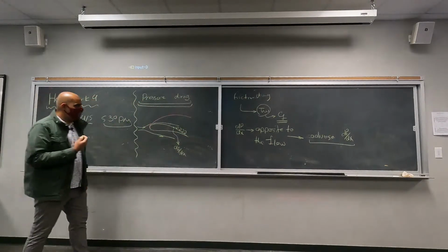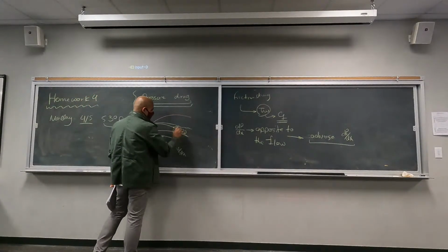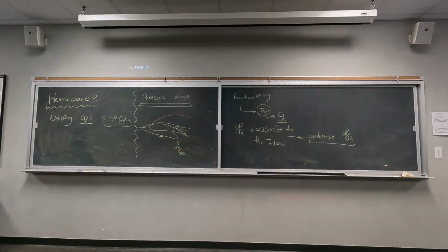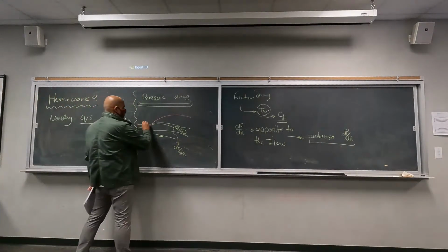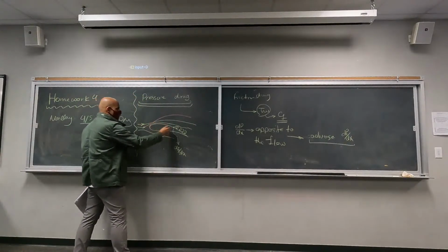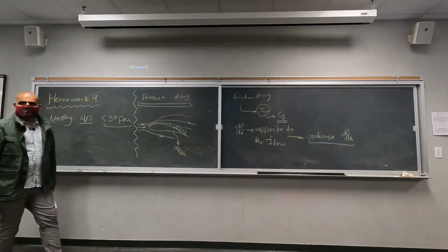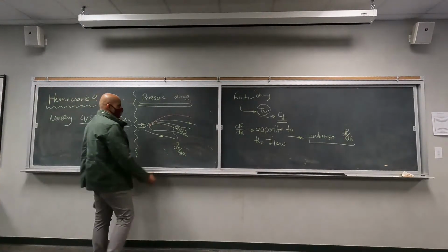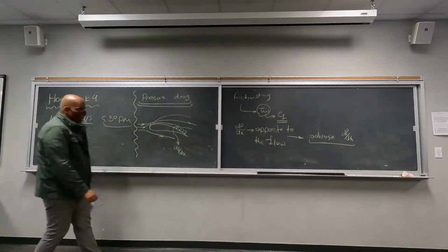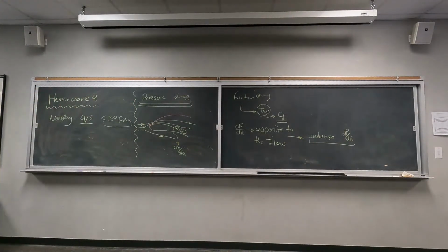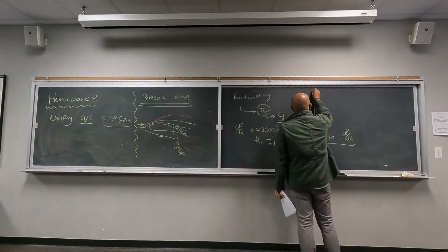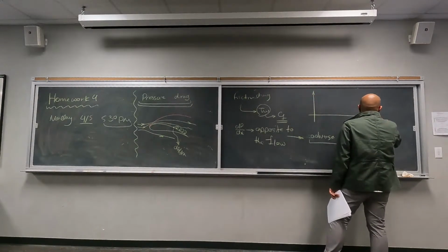And this is something we call flow separation. So the real flow field, fluid particles moving from this location to this location, has separated from the airfoil. Flow is moving in this direction. This is going to cause a lot of problems in general for our flow, but the main one is its effect on the pressure.